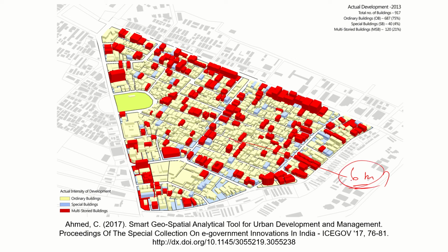not even a two-way lane. First, for two-way we said 7.2, right? Even we have lanes which are just 6 meters, and we have multi-storied buildings there. In fact, now I don't know, if we do an assessment, probably all of this should be red. This is still 10-year-old data now, almost 10 years old. So we use GIS for simple applications like this as well.